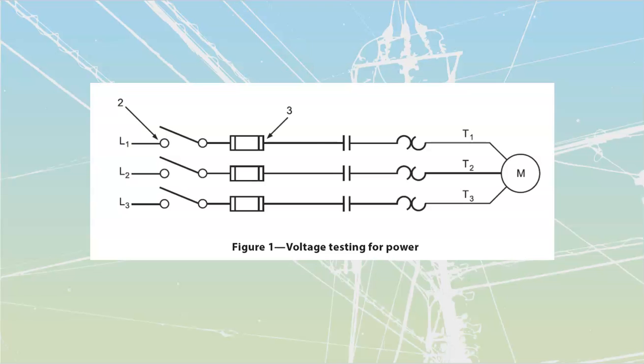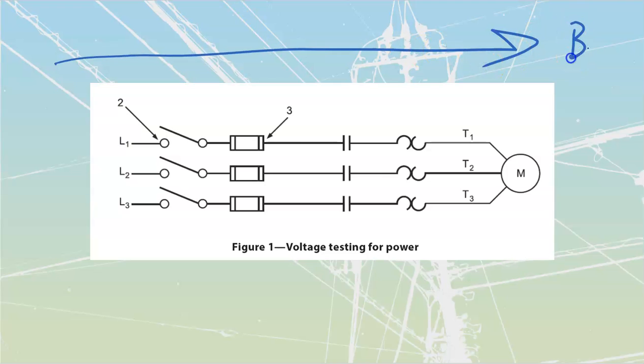If the motor is not operating, we're going to work our way through a control system, starting from where we know we should be good, working all the way back down to where we know that something has gone badly. So over here we've got bad, over here we've got good. We know that whatever happens, we should always have good power applied on my lines, so I can start working from there all the way back through.